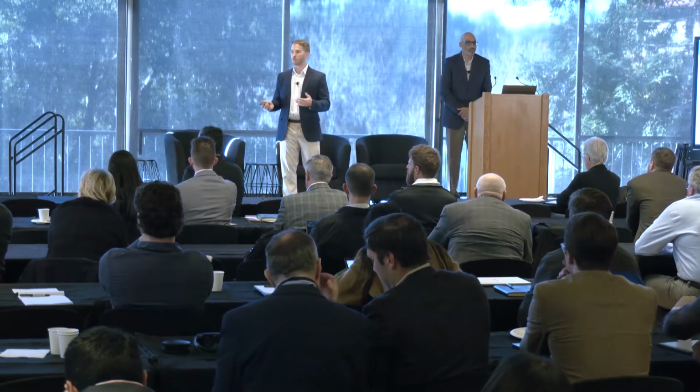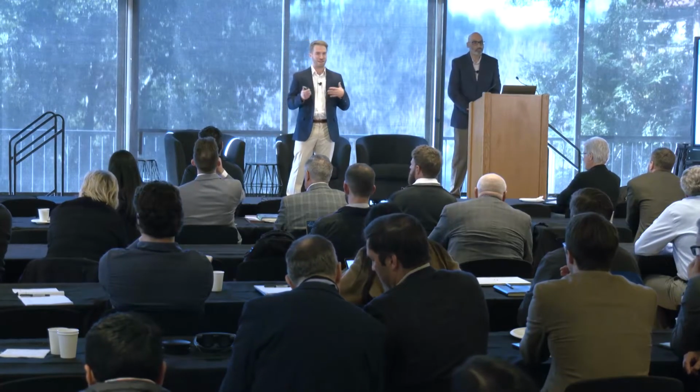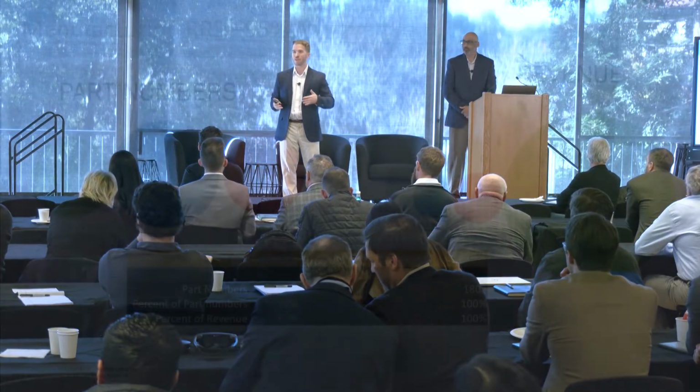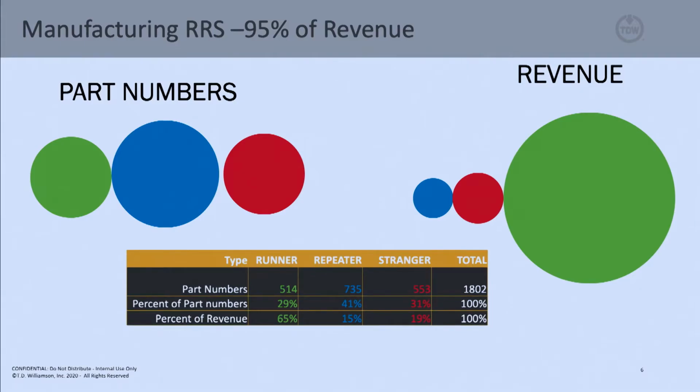So how are we gonna create CONWIP loops or implement WIP control in our factory around these 9 bottlenecks? I mentioned it was spaghetti, and that spaghetti goes everywhere. And so across these 9 bottlenecks, we could have the same routing that goes across all 9. And that's frequent. Those machines that do a lot, they do a lot. So we had to figure out how we were gonna do this. So we got together our production team, our planning team, and some of our other plant managers, and we were telling them, you know, we can do the model by different types, by different sizes, but every time we try to put a flow together, there's so much overlap, we were having a hard time.